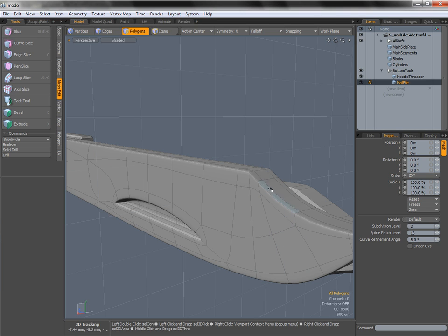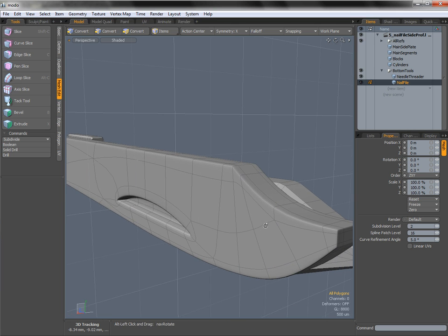To get that change, you'd have to come in and physically add in extra detail. So all of the things that Modo is adding in to the mesh, all of the extra polygons, extra edges, and the extra verts cannot be edited by you. That's in the normal tab mode. Using SDS Subdivide, however, gets you access to those verts, to those polygons that Modo is creating behind the scenes.